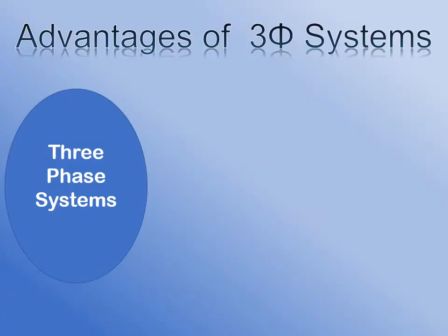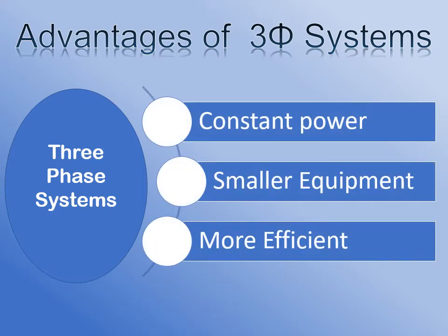Nikola Tesla was the first one to work with polyphase AC systems. And he observed that a three-phase system was the most efficient way to produce, transmit, and consume electricity. When you have a three-phase system, it's unlike a single-phase system. When you have a single-phase AC power, the single phase pulsates and falls to zero. Whereas in a three-phase system, the power never really falls to zero. The power delivery to the load is the same at any point or any instant.